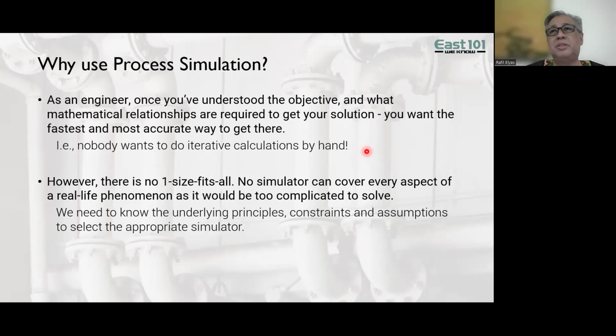You use something like HYSYS or Unisim or Petrosim, and these are thermodynamic equilibrium based tools. But real life isn't just thermodynamic equilibrium. You've also got mass transfer, momentum transfer, heat transfer, which skew things away from the ideality that thermodynamics typically represents. Hence, we really need to understand what some of the underlying principles and constraints are when we're working with the software tool.